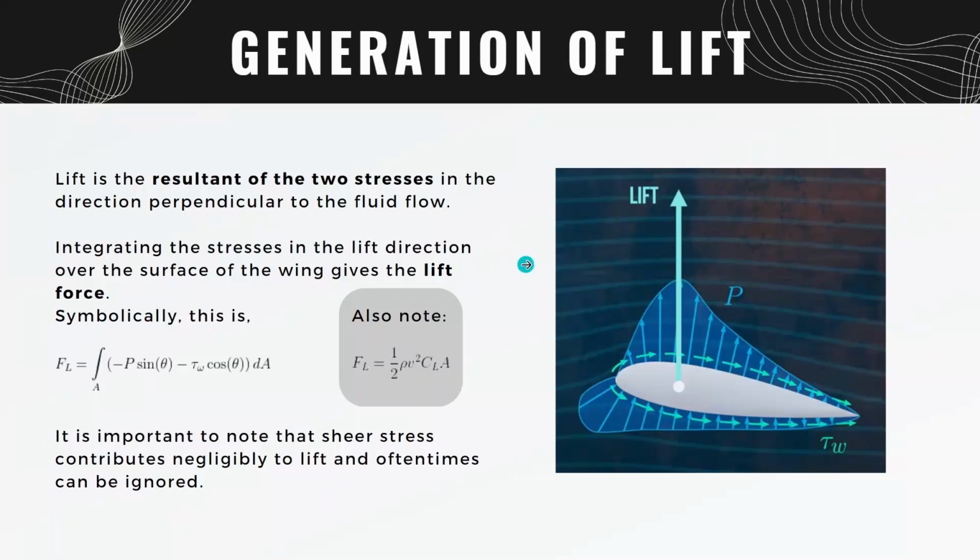Now, one important thing to note is because the shear stress is almost perpendicular to the lift direction, it almost plays a negligible role towards the force calculation of lift. So we can, in most cases, ignore it.